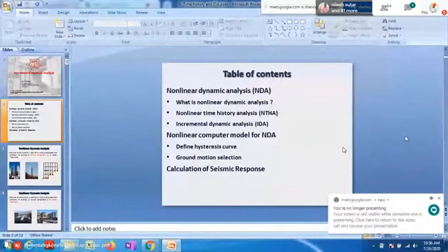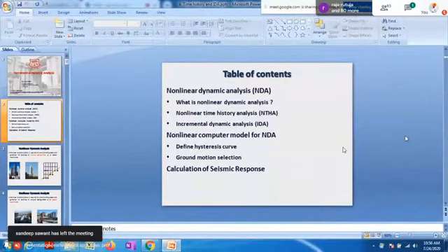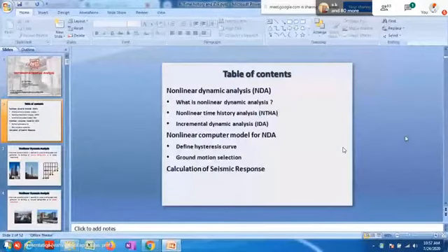Many sites are there. For example, for severe ground motion records, researchers usually prefer the PEER strong motion records. The Pacific Earthquake Engineering Research Center is in California. Many strong earthquake records right from 1940 are available on that site. In India also many research centers are there. IIT Roorkee also has its own site and some records. So from those stations we have to get ground motion records to perform this.